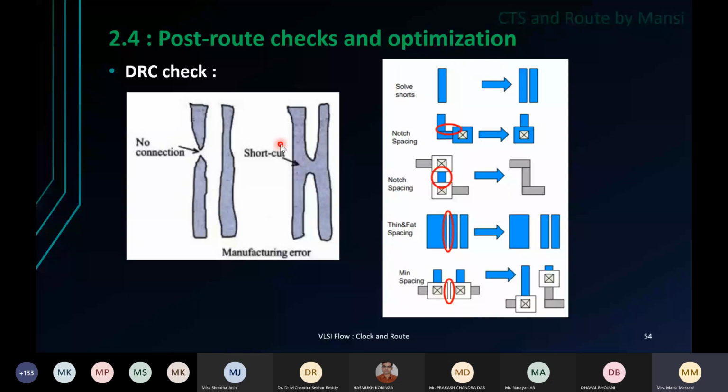Now, these are some DRC violations. This violation says that you cannot have a via very close to a vertical layer, so you basically cannot have a notch, and it moves the via like this. Then it says you cannot have two vias with this much spacing close by. So it says, I don't want a notch, so I'm just going to traverse my net like this. Then this is another design rule violation, where if your metal width is this much wider, this small space is not allowed.